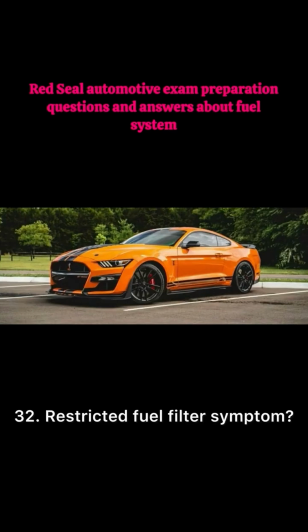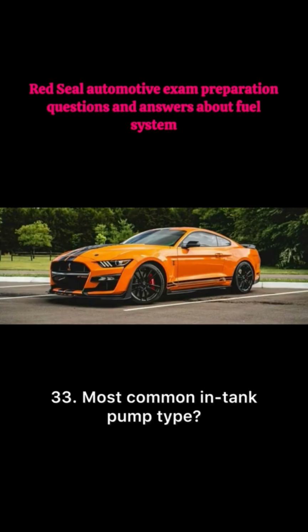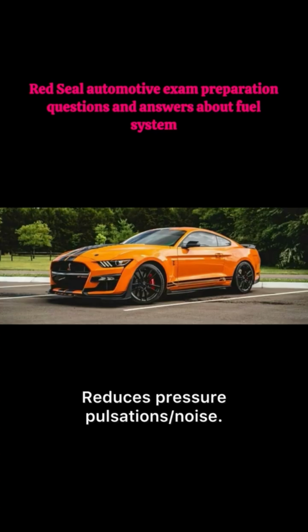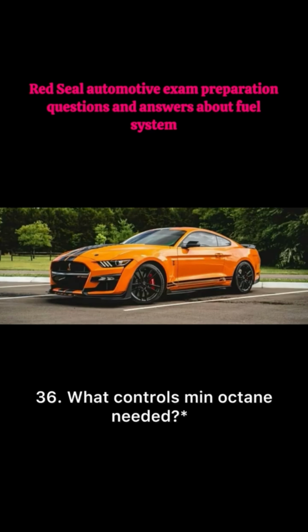32. Restricted fuel filter symptom. Loss of power under load. 33. Most common in-tank pump type. Turbine or gerotor pump. 34. Fuel pulse damper purpose. Reduces pressure pulsations, noise. 35. EVAP vent valve stuck closed code. P0446.